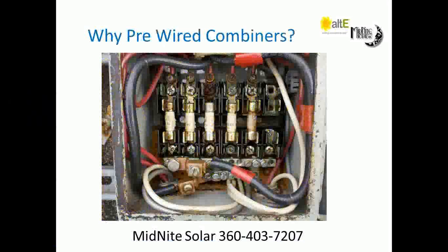And again, that holds true for everybody except SMA. SMA can tolerate about a 2-to-1 ratio, and if there's a Sunny Boy in the system and you really want to get fancy, you do the Sunny Island and you will get frequency dithering, and it will not just shut it off. It will throttle it back to keep the batteries properly charged.